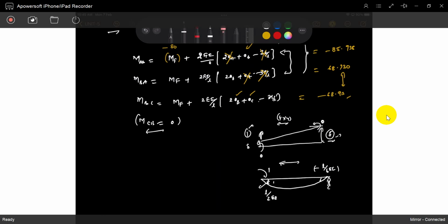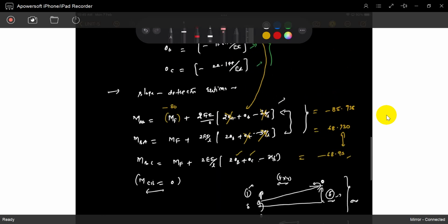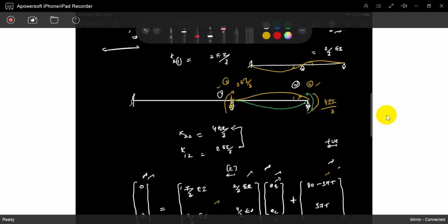So by the flexibility matrix you can solve problems only like this, only 2 by 2, 3 by 2. Some of these are arrested here. Now you can see some of the forces you can arrest here. If you see only rotation, there is no deflection, because you arrest something, the vertical reaction, you can arrest it.